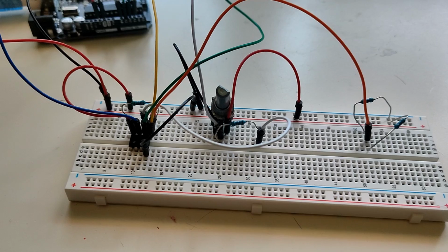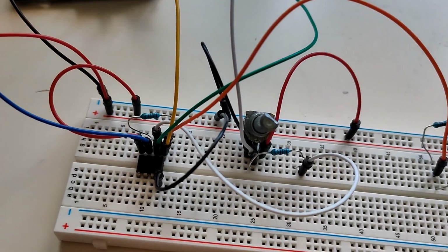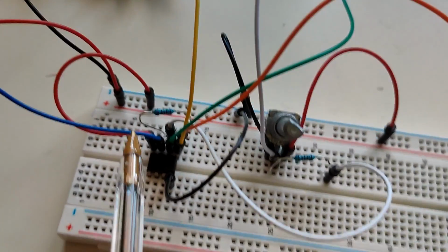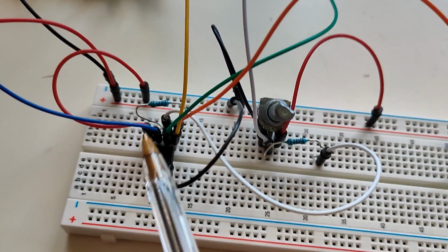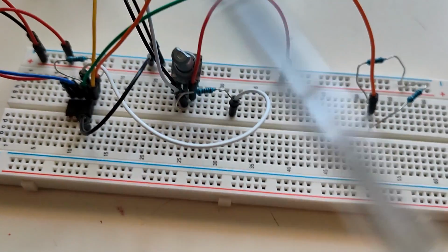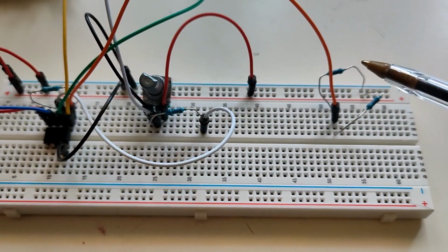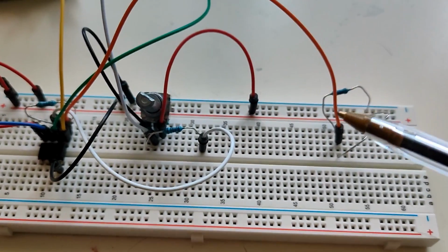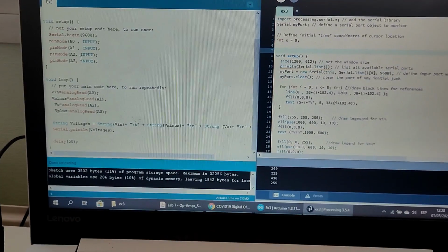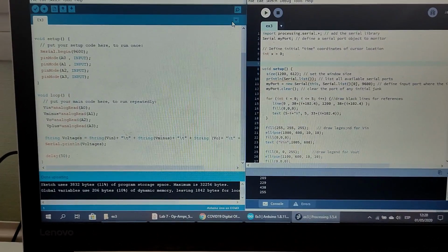In phase 3, we were building an inverting amplifier circuit. For doing so, we placed a resistor of 10 kilo ohms between the inverting input of the amplifier and the voltage output of the amplifier. For the non-inverting input of the amplifier, we're using a voltage divider to maintain that value at 2.5, which would be like a ground for our circuit. Coming to the Arduino code, we didn't change anything. We just added another variable for the non-inverting input, the voltage plus of the amplifier.